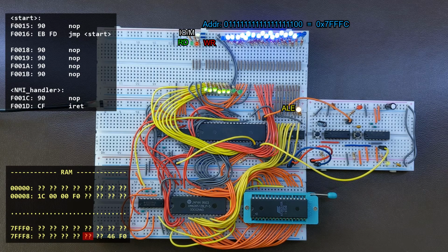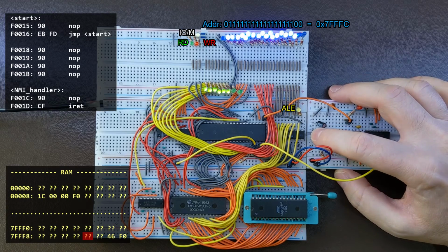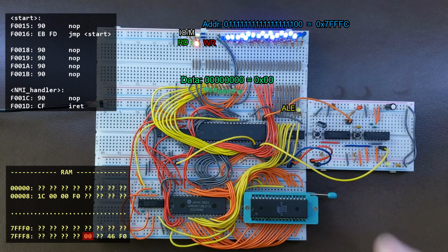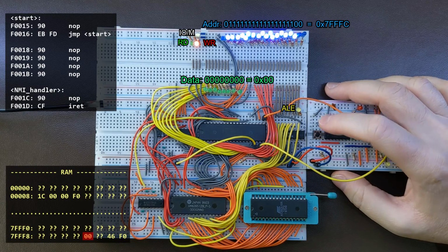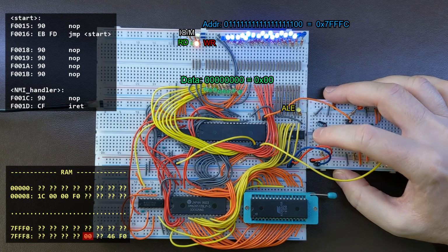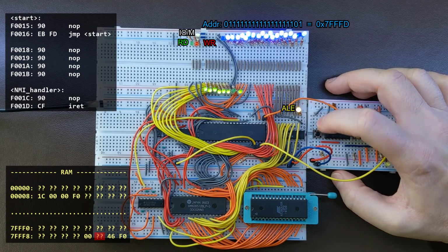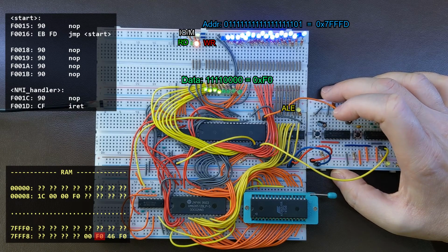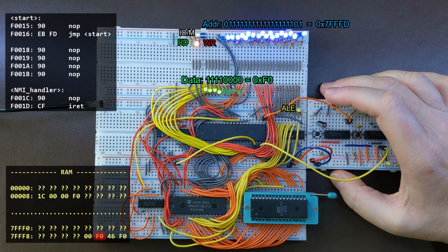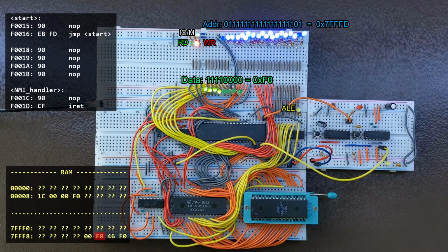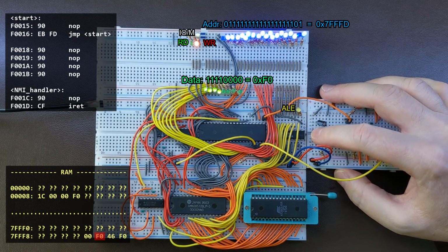And that's what we expect should be the current value of the CS code segment register. And it's writing 0, that's the least significant byte of the F000, so that's 00 currently. And the next transfer, we expect it to be the next byte in the RAM, and the most significant byte of F000 is, as you can see, F0. So that's all fine.